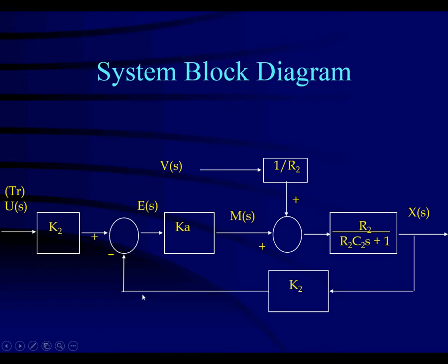And that electrical signal, compared to what you get of the feedback, you get the error. In this case, deliberately, we are making the correction with proportional control, just with a constant. And what you see on the left-hand side are the disturbances that we need to account for when we design controls. So you will see this is trying to control, and then this in here creates a disturbance.